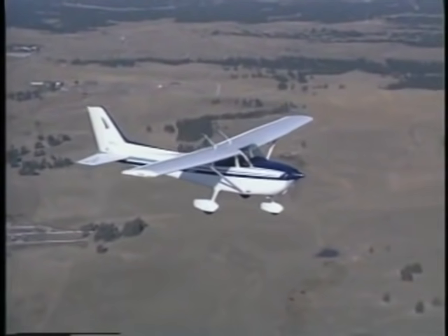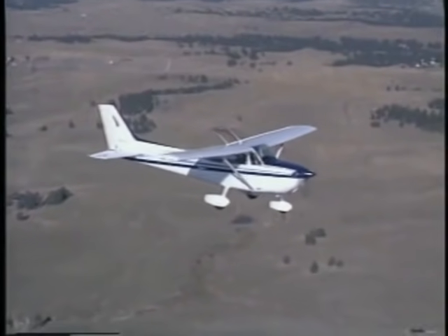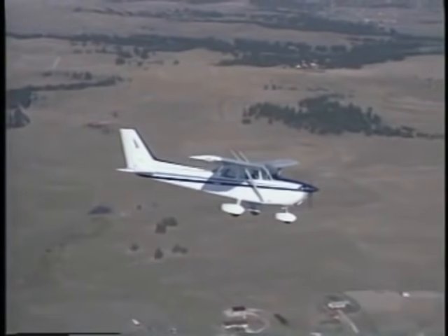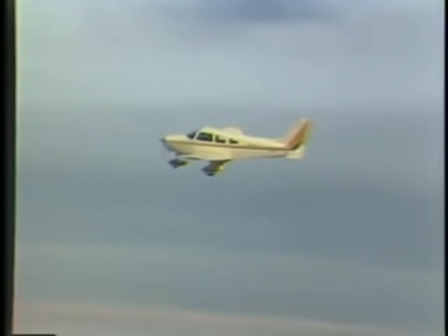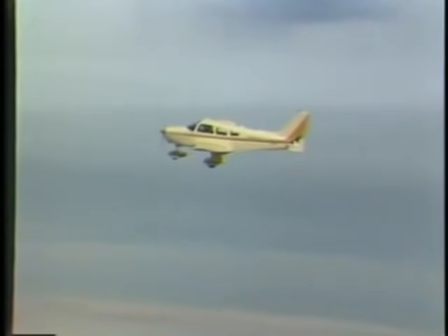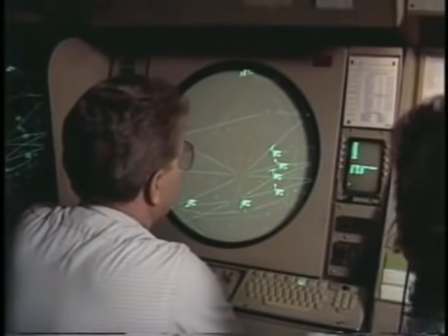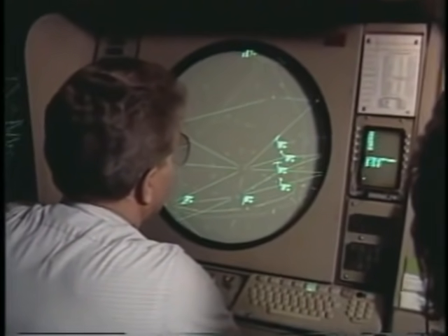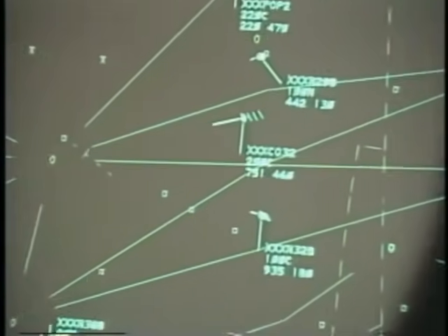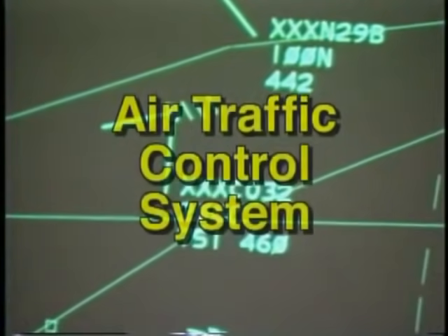When flying in VFR conditions, you're required to maintain specific visibility and cloud clearance minimums. Instrument flight rules allow for appropriately rated pilots and specially equipped aircraft to fly in weather where normal VFR flight would be impossible or very dangerous. When you're flying in IFR conditions, seeing and avoiding other air traffic may be impossible due to the lack of adequate visibility. During these periods, you must rely on the air traffic control system to keep your aircraft separated from other IFR traffic.